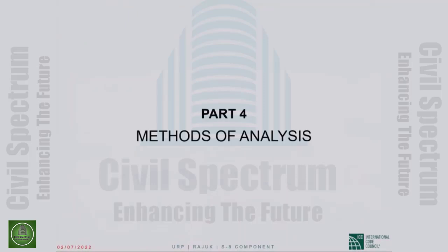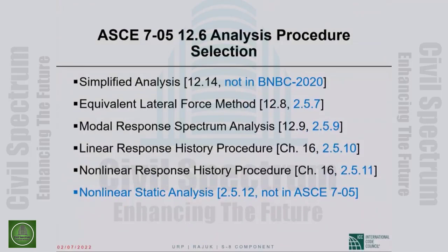Then, as you see, methods of analysis. From the beginning of seismic design, as I understand it, we have made a big deal of these analysis procedures: whether the equivalent lateral force procedure that we use much of the time is good enough for certain structures, do we have to do dynamic analysis, and so on and so forth.